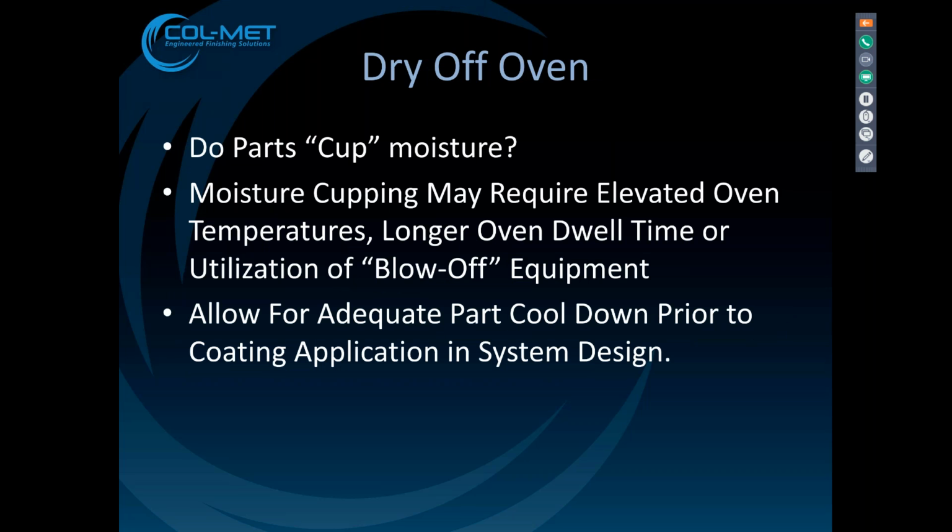After we wash, we have to dry the product off. One thing we have to consider as we dry off is, do parts cup moisture? Most companies will do the very best that they can to hang their parts so that the parts drain and therefore they don't cup. But there's some product configurations that there's no way around it. You just can't help but that the part's going to retain some moisture through the washer.